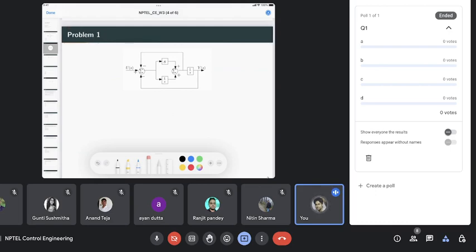So as I said, we can use both block diagram reduction, or you can use the signal flow formula also, right? So let's first try with block diagram reduction, then we'll try also with signal flow. As you can see, one thing you can easily simplify is this block. It is just simply two signals that are summed there inside, right? So you can add them, this gain, and replace this with a simplified term, which is just one. Instead of that, you just replace it with some block. Then your simplified version will be okay.